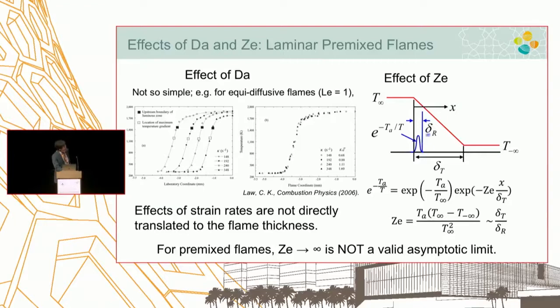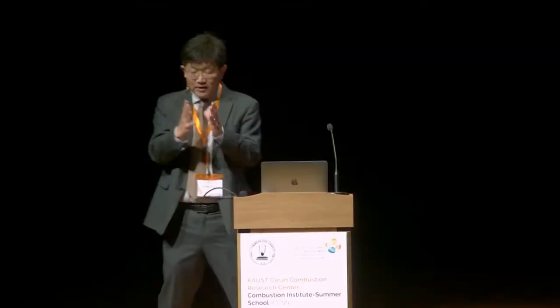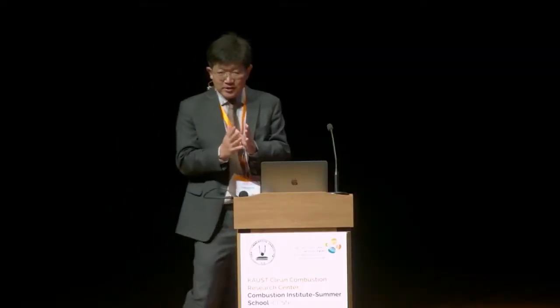The preheat zone thickness is governed by convection and diffusion, but the reaction is focused only within an order-of-magnitude thinner layer. However, the nature of the premixed flame, in summary, is always a reaction and transport balance. There is a perfect one-to-one match to establish premixed combustion.